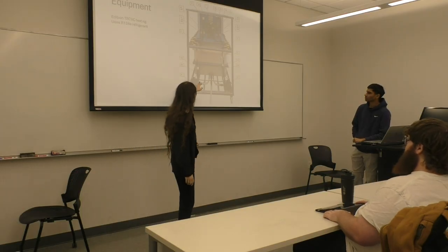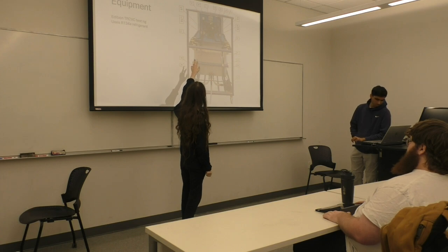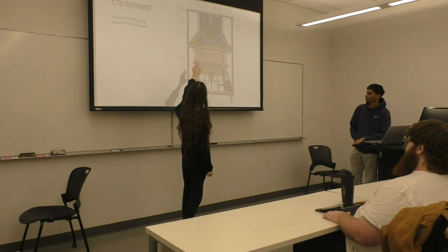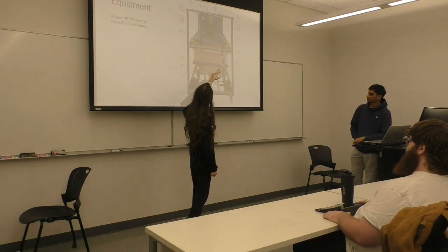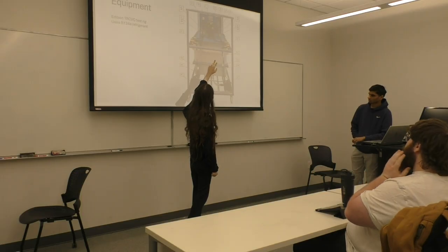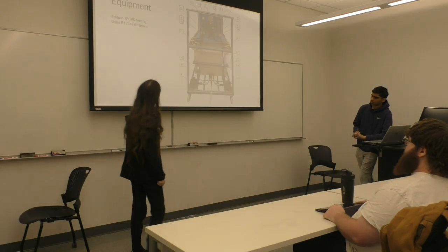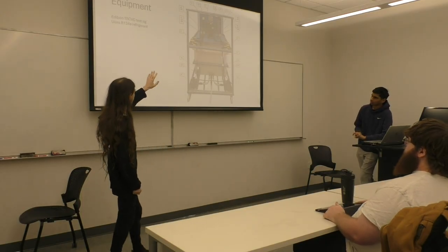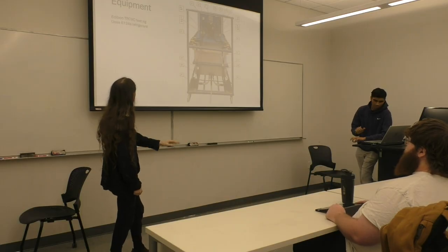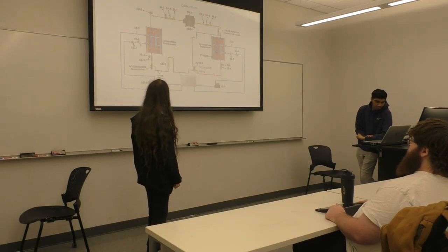On the bottom is a reservoir of water, which gets pumped up through the condenser, which is on that side, I think, and that side is the evaporator, the compressor is in the center, and the top is the expansion valve. There are various sensors and gauges that measure all the pressures and temperatures at various points.